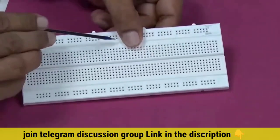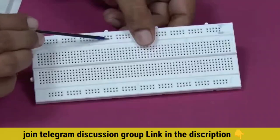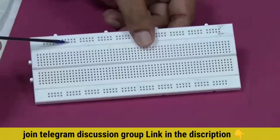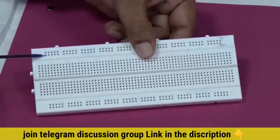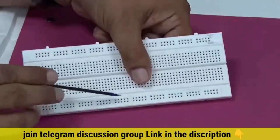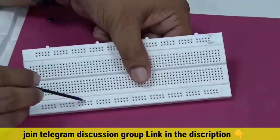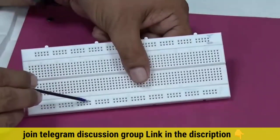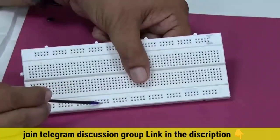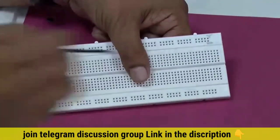Similarly, if you go to the next line, there are 25 holes there, 5 here, then 5 here, and so on. All these 25 are internally connected to each other. And similarly is the story on the other side, and on the bottom side. Here also all these holes are internally connected to each other on one longer line, and on the bottommost line also, all these 25 are internally connected to each other. That's it. And similarly for this side.